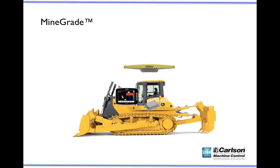Same thing with a dozer. I could use the heading unit and get true heading, one cable to the CBX5, and then depending on the size of the machine, I may or may not need a body pitch and roll sensor. Or I could forego the all-in-one heading unit, the all-in-one sensor, the VX5, enable the internal GPS plus GNSS receiver inside this box, add the antenna and the RTK radio. Or I could stream an RTK correction via the SIM card slot inside the CBX5 control box.